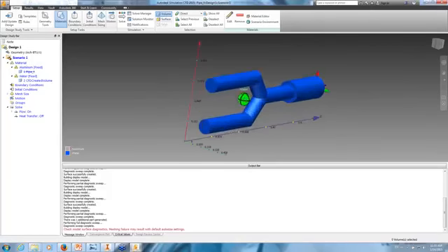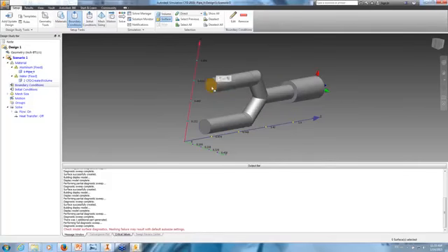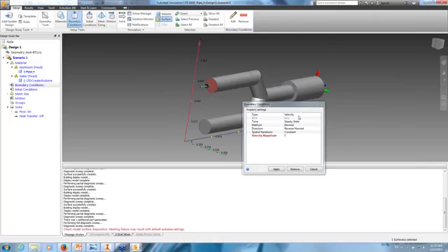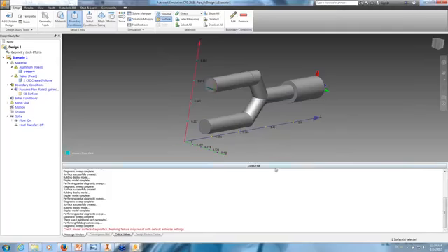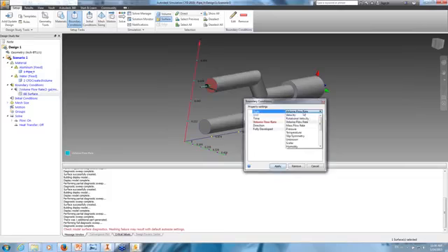What I'm going to do here is go to boundary conditions. I will select this surface, edit. I'm going to do two things. I'm going to specify a volumetric flow rate of 3 GPMs here. So I'm going to go down to gallon per minute and set that to be 3 and apply. I'm also going to set that at a certain temperature, so it's going to come in at 50